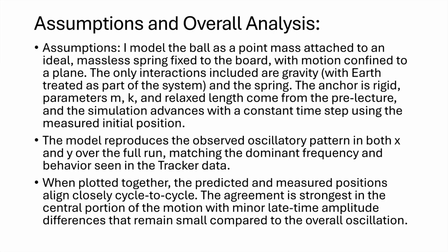So assumptions and overall analysis. I model the ball as a point mass attached to an ideal massless spring fixed to the board with motions confined to a plane. The only interactions included are gravity with Earth treated as part of the system and the spring. The anchor is rigid. Parameters M, K, and relaxed length come from the pre-lecture, and the simulation advances with a constant time step using